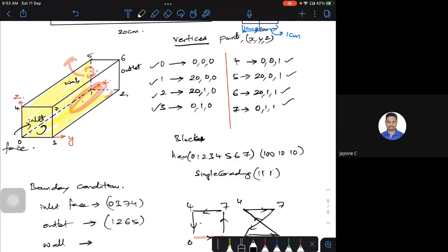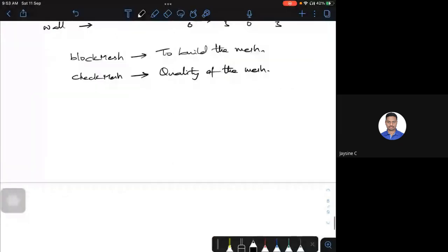Yes. Okay. Now, I told you there is a folder called the constant folder. In that, you have a file called turbulenceProperties. In the turbulenceProperties file, you have to define whether it is laminar or turbulent, all those things.